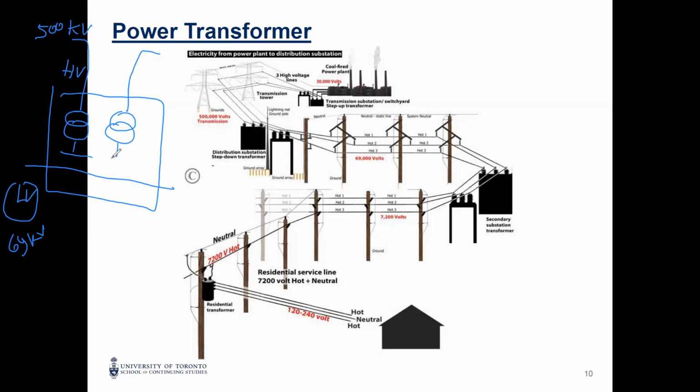So with 2 transformers, sometimes we put them in parallel, but usually we put one breaker here. Sometimes they work in parallel, connected to each other. Sometimes we open this, but then they are connected to multiple feeders at the low voltage, and each one has its own breaker, of course.